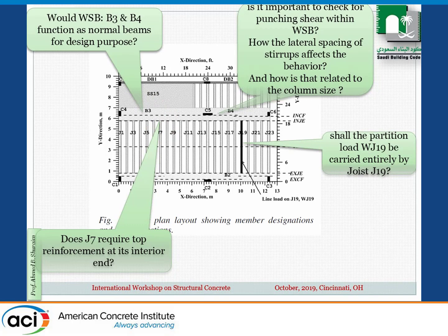I mean, of course, if we are considering this to be a rigid beam, yes, the answer is yes, it's the typical thing. However, considering this situation, we've done a lot of experimental work. We made a complete building here, and we also modeled it with finite element simulation and found consistent results. No, it's not working as it looks. If I simply assume this is a beam, it's not a beam in that sense.